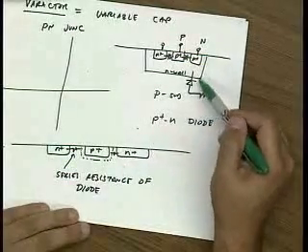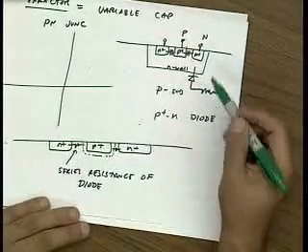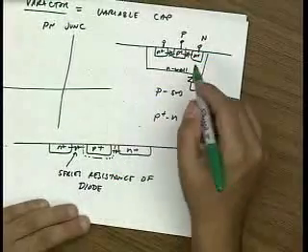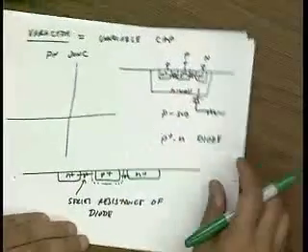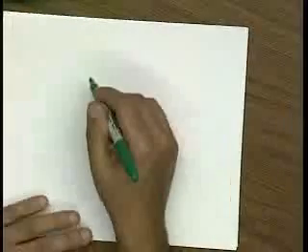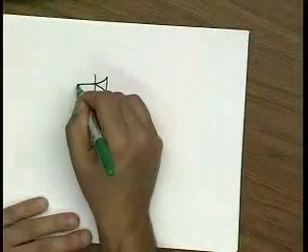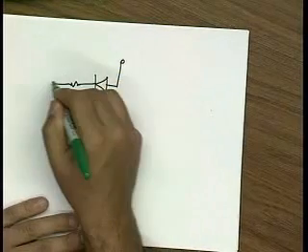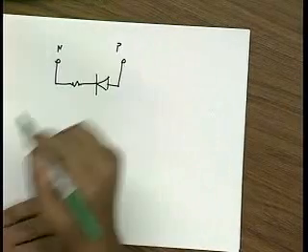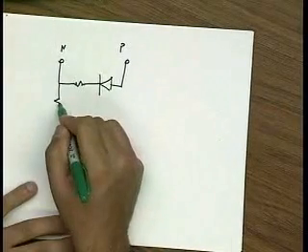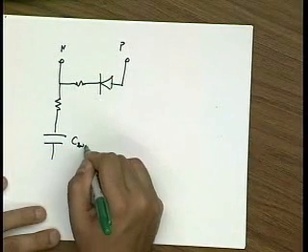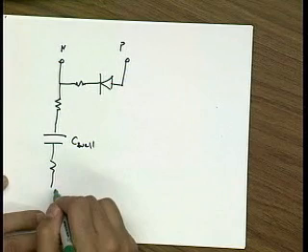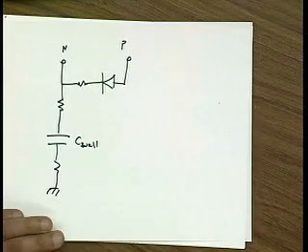This over here introduces another parasitic. So maybe the equivalent circuit that we can draw for this capacitor, draw it over here, is I have my cap, some resistance. This is the P, this is the N side, but then the N side also has some resistance and then some well capacitance and then some more resistance to ground. Okay?